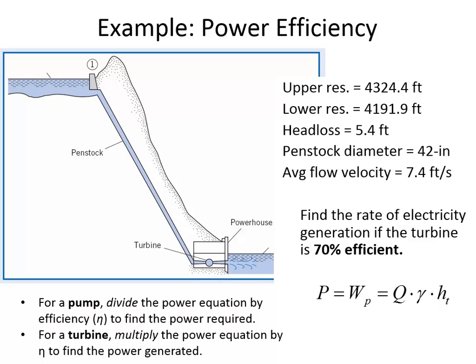So here, if we apply the energy equation between the two reservoirs, location 1 is always the upstream location. Location 2 is always the downstream location. Remember that this equation has a directionality assumed that you have to honor, otherwise you're going to get the wrong answer. The directionality is that flow goes from 1 towards 2.